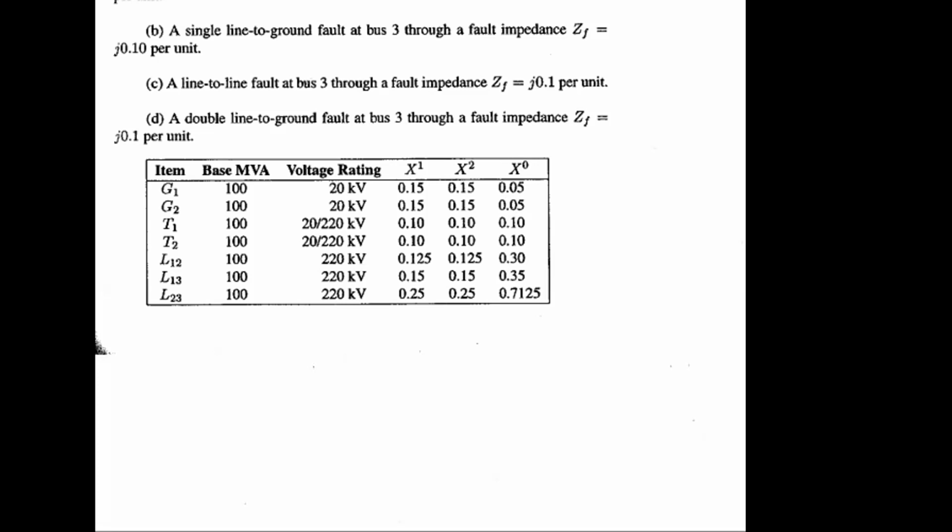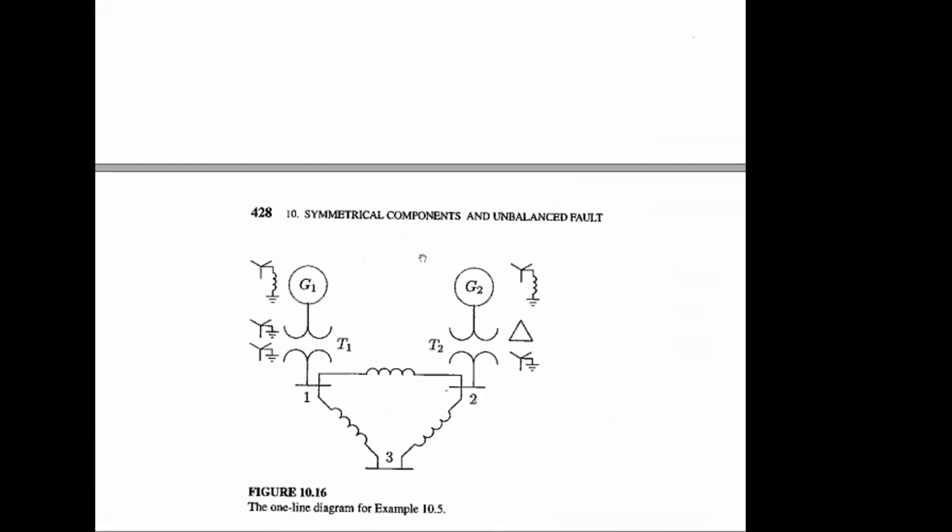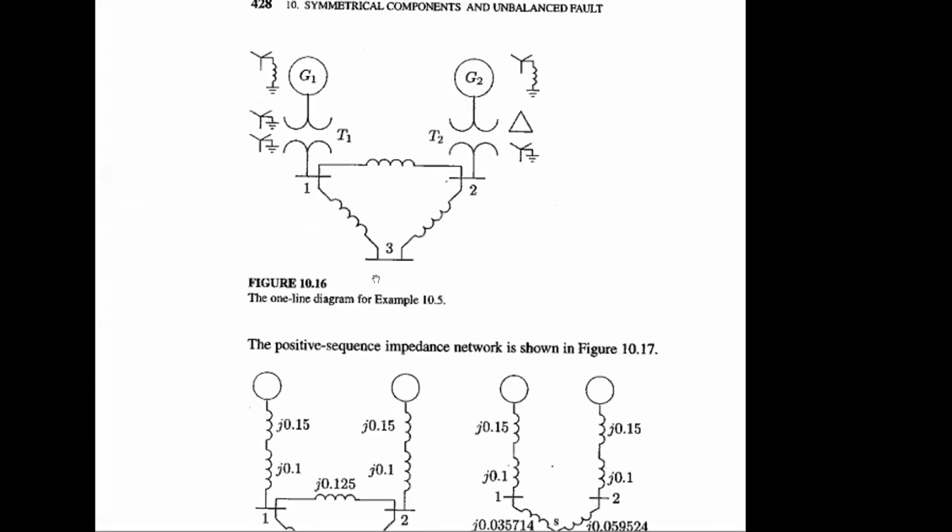And another important consideration regarding the transformer part, when you want to put this information, transformer 1 and 2, you have to be careful about the equivalent circuit for zero sequence network. Okay. Zero sequence transformer network, you have to draw according to the connection of transformer primary and secondary. For this case, transformer T1 and T2 are different, right? Internal connection. So you have to draw the connection when you want to draw the equivalent circuit.